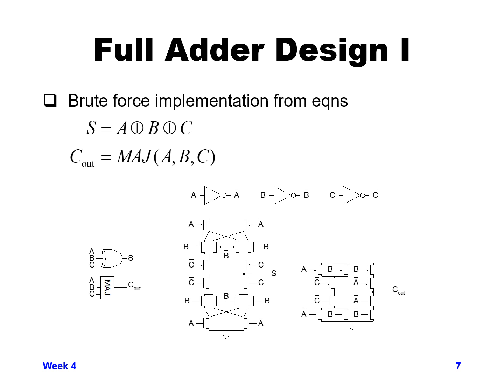Then on the right-hand side is shown one possible way to create those two values. First of all, for this particular function, we need A and A bar, B and B bar, and C and C bar in order to create this implementation shown here. So we have three inverters needed, and then the left-hand circuit shows us how to create your sum value in a single gate stage for the XOR function. So that is a way to do a 3-bit XOR in a single stage to get sum out.